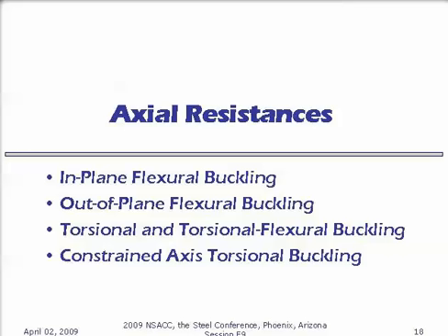We have various ways that are provided in the design guide that give you instructions on how to best calculate that buckling value, that elastic buckling value. But the concept of then mapping that to an elastic or inelastic buckling strength is really the same thing that George was doing in his work.